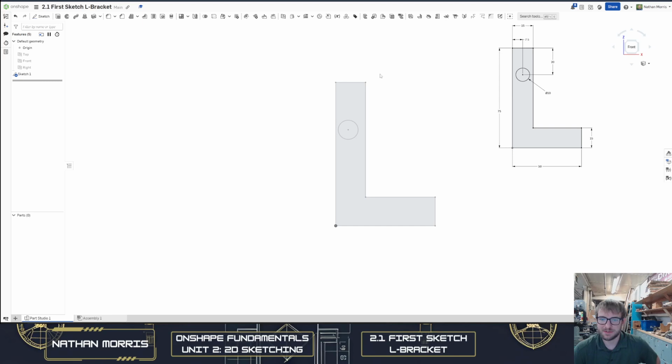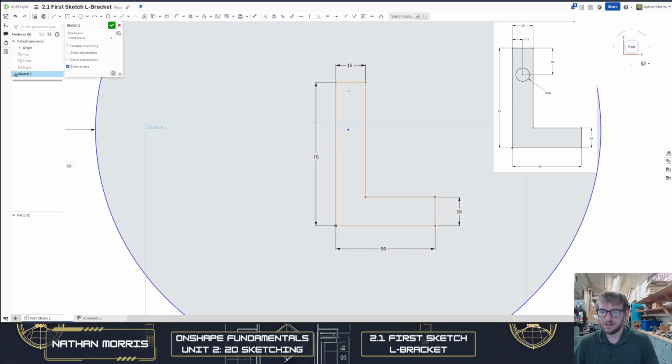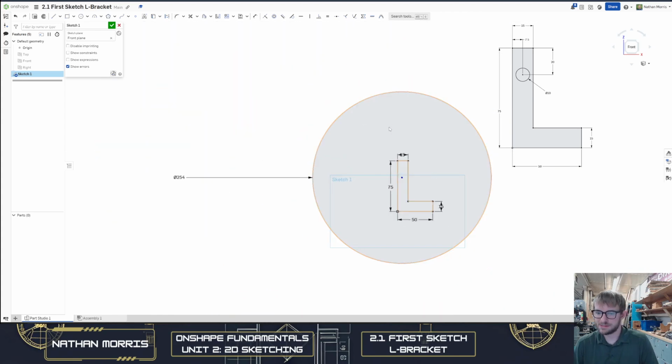But when you add a dimension, by the way, I closed out of the sketch when I did that, so I can double click on Sketch 1 here, and it brings me back into editing this. If I double click on this dimension, see it says 10 mm. I could also set it to 10 in for inches, and you can see the difference in scale.